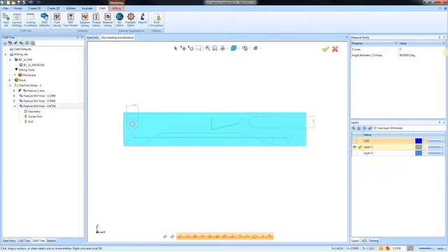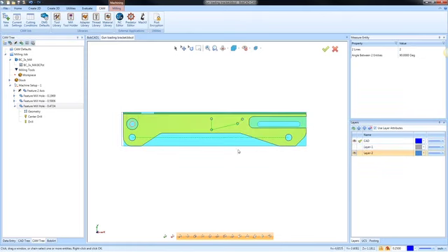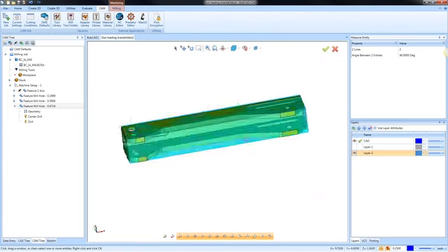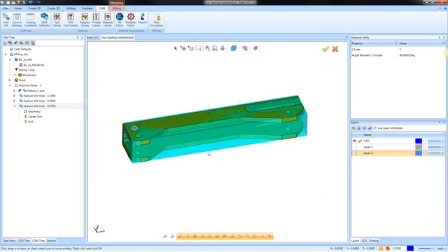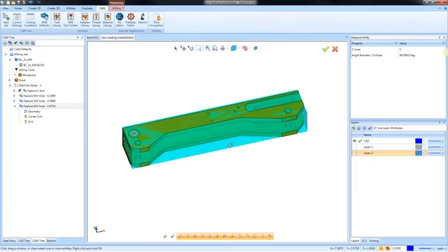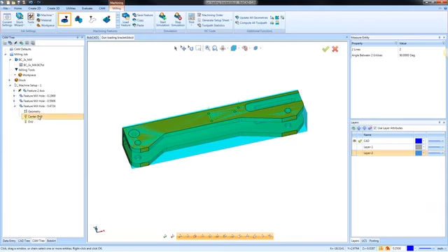Hopefully that makes sense for you there, Thomas. And hopefully, Paul, you're clear on working with wireframe for drilling. Same process. So we've created some holes here now. With drilling, you could have them start and stop at different sizes. You can load in a spot drill, a drill. You could do tapping, counterboring, all that kind of stuff. No big deal.